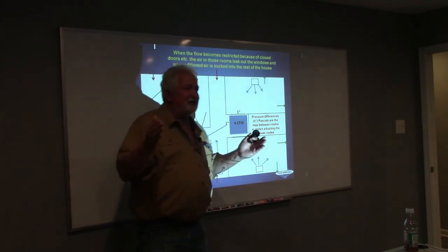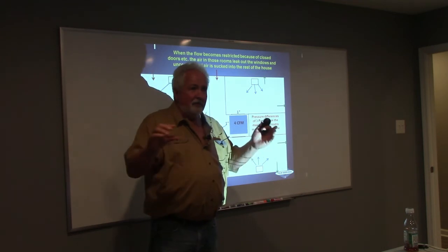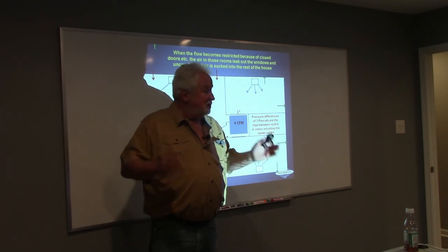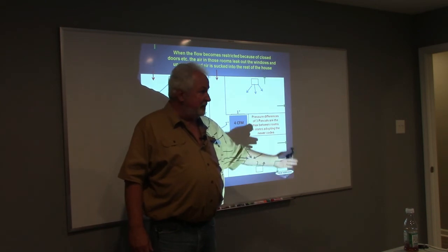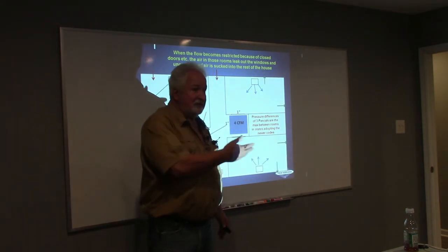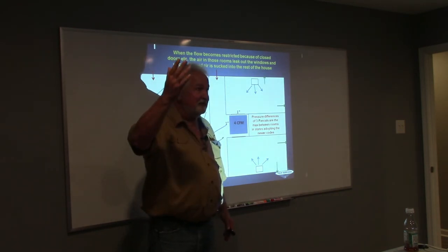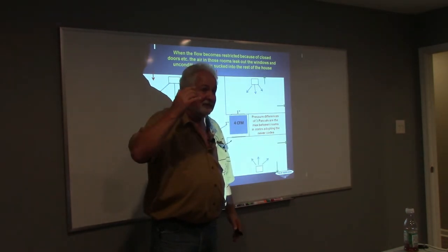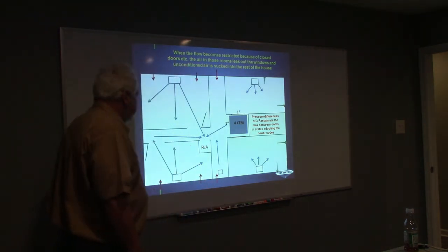So if I have a 30-inch door and I cut off 1 inch, 1 times 30 is 30, times 4 CFM is 120 CFM. So if I cut off 1 inch off of the bottom of that door, and it's a 30-inch door, I can move 120 CFM under that door. But if I got 250 CFM in here, I'm going to have to cut off another inch off of the bottom of that door. Does that make sense? Real quick and easy, yes? Good stuff.